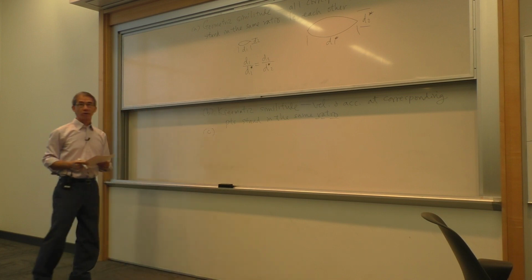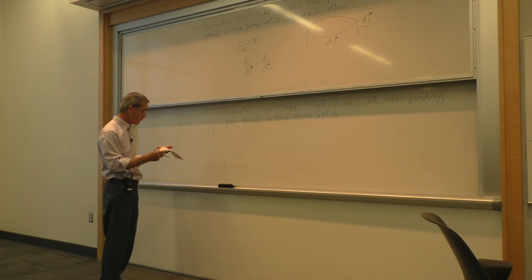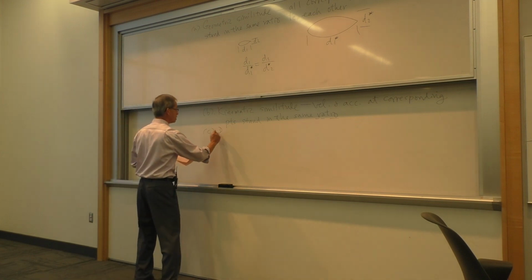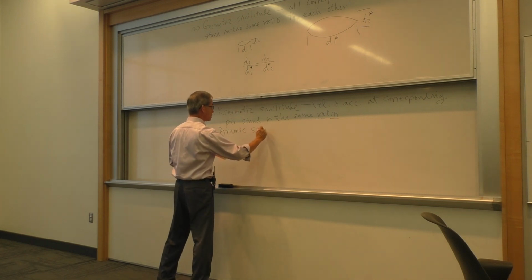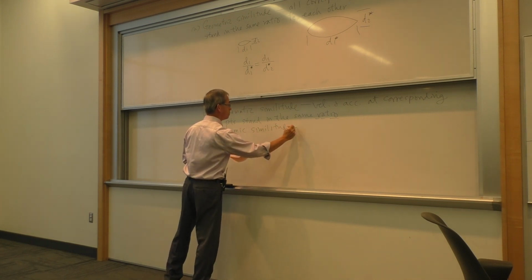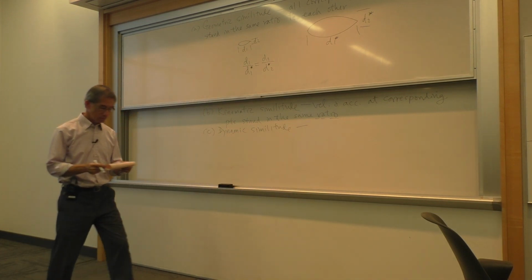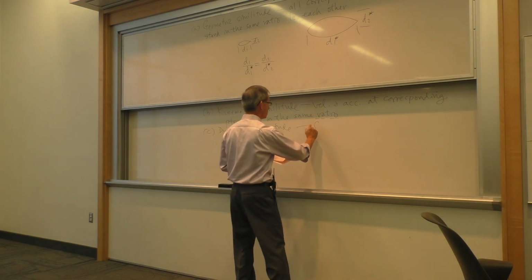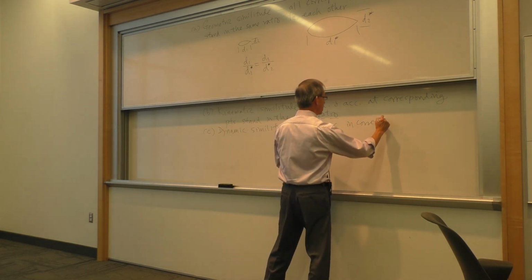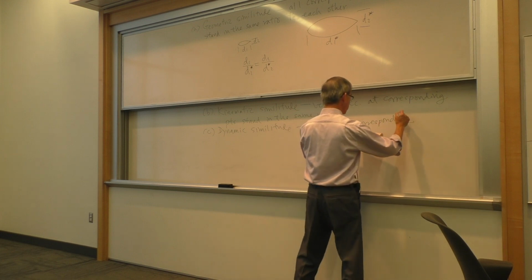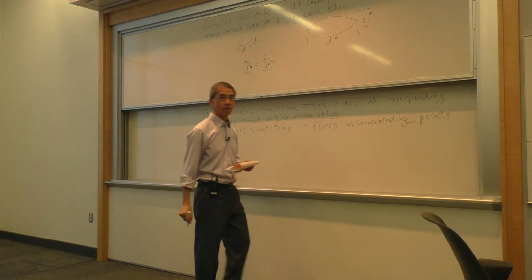So velocity field and acceleration field have to match point by point. The last one is forces, which we call dynamic similitude. Forces, F equals ma, on all points must also stand in ratio to each other. How is where we will further illustrate by example and by the homework.